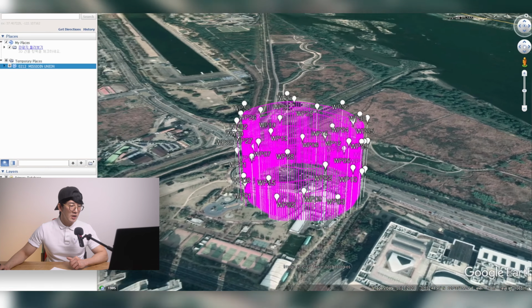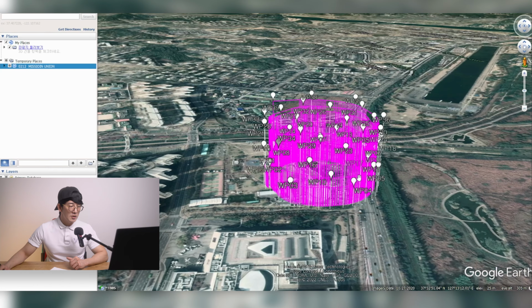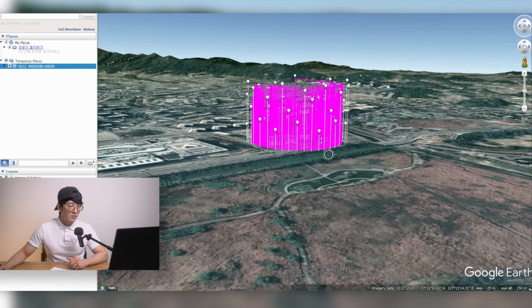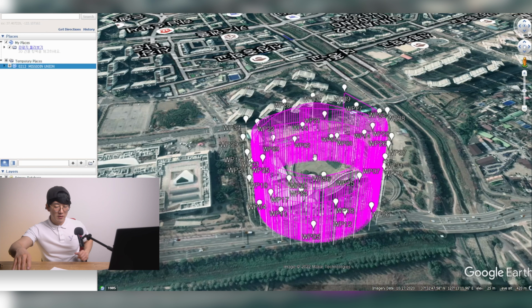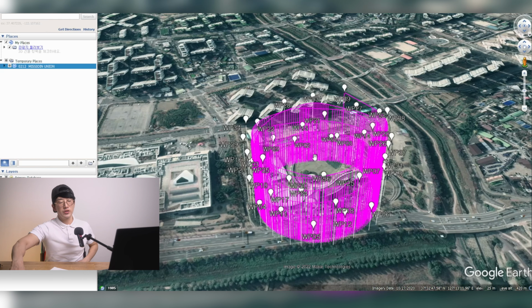When it flies, it just changes the altitude gradually, increasing until the top of the buildings, and then at the end of the mission, I manually fly the drone. I capture the top of the building. So with the -90, I capture like this and this. I didn't want to miss any space, so I captured it 3 times at different angles.